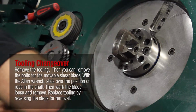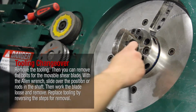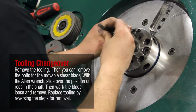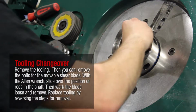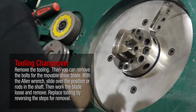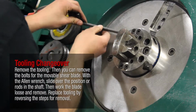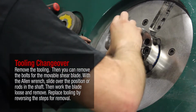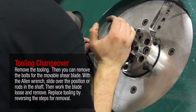Remove the tooling. Then you can remove the bolts for the movable shear blade. With the Allen wrench, slide over the position rods in the shaft. Then work the blade loose and remove. Replace tooling by reversing the steps for removal.